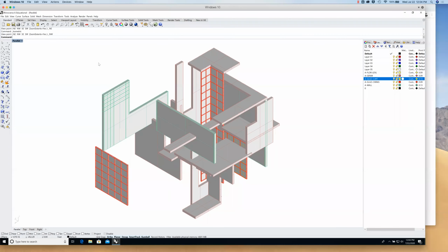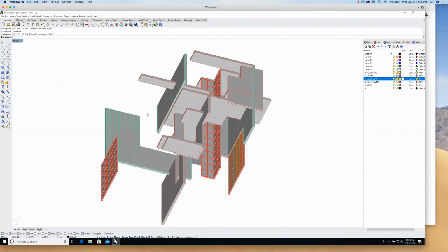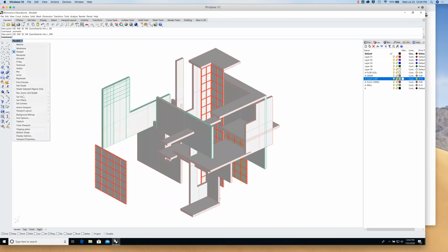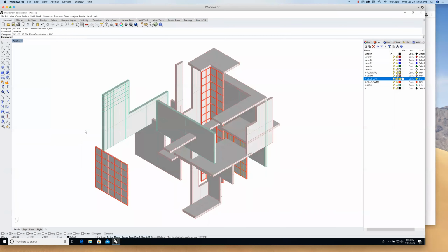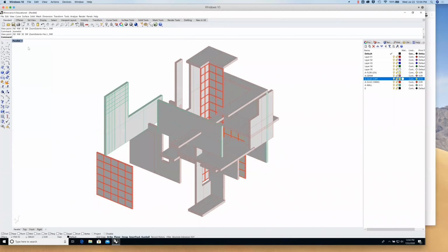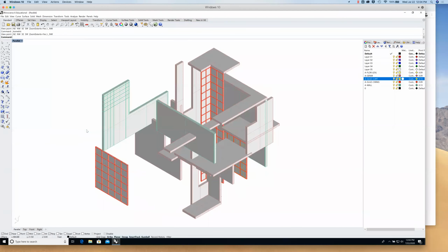All right. So again, a couple of things. A few of you, not most of you, I noticed somehow messed up your isometric. It looked like this, or it wasn't a 30-30. Always go back and make sure that this thing is set to that 30-30 orientation, right? I can right click with my mouse and rotate my view around anytime I want. But when it comes time to do the make 2D, I want to make sure that it's very precise.